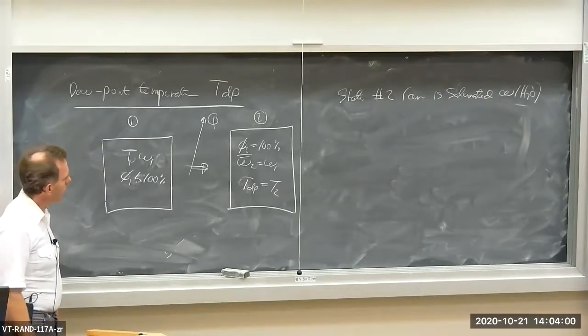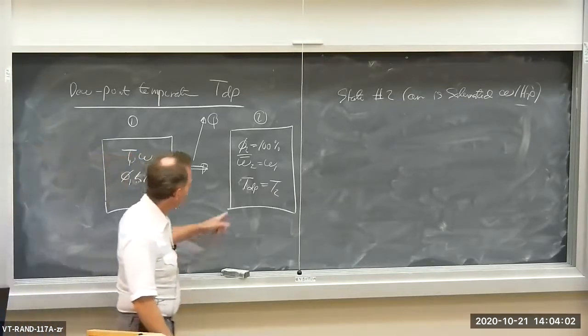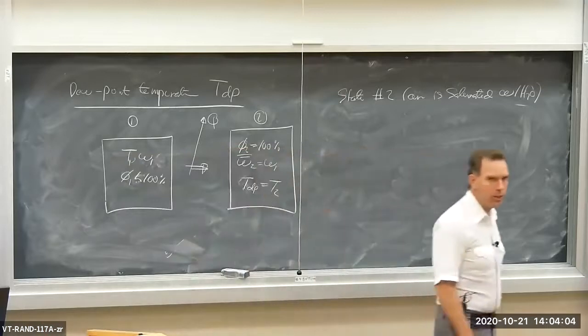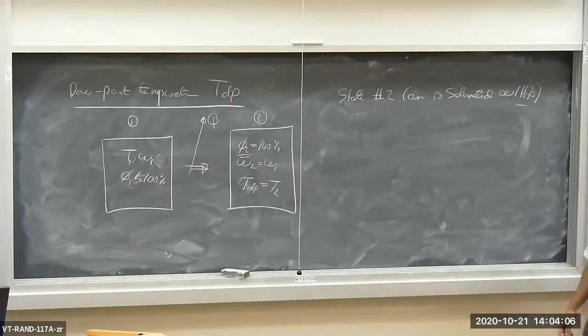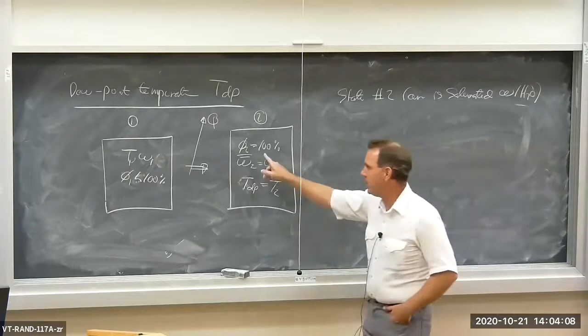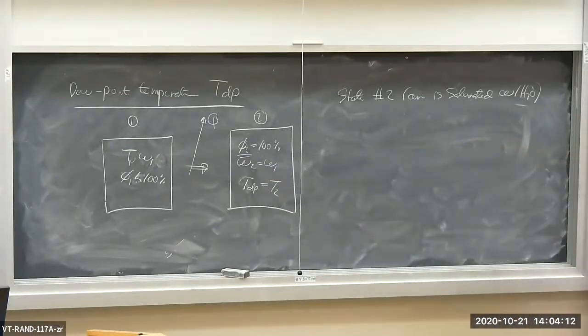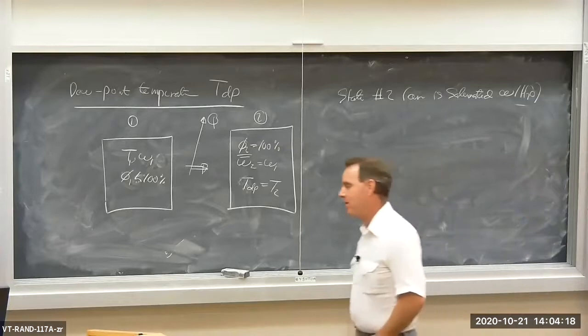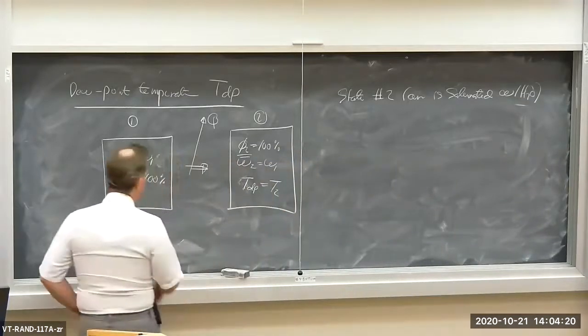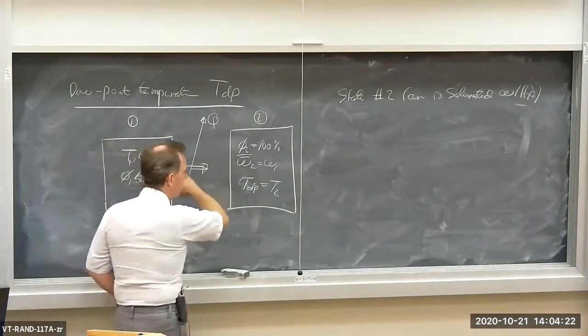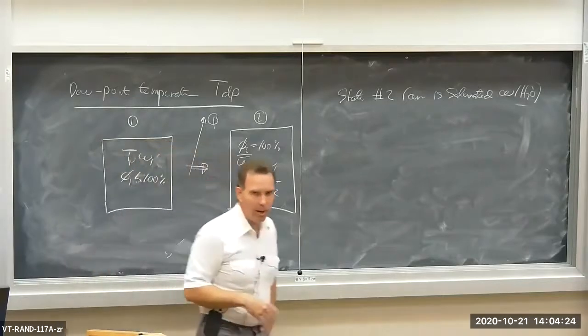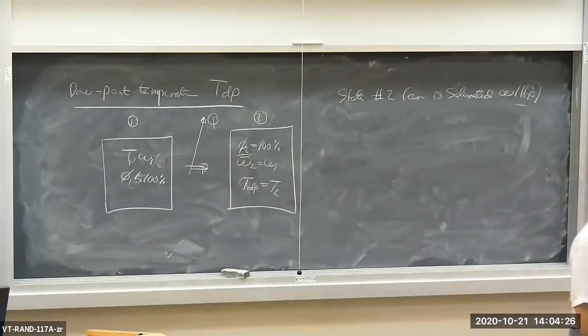Now what I'm going to do is extract heat, cool down the mixture until the relative humidity is 100%. So I'm reducing the temperature and therefore reducing Psat. The amount of moist air is constant in this container. I'm not adding any H2O.